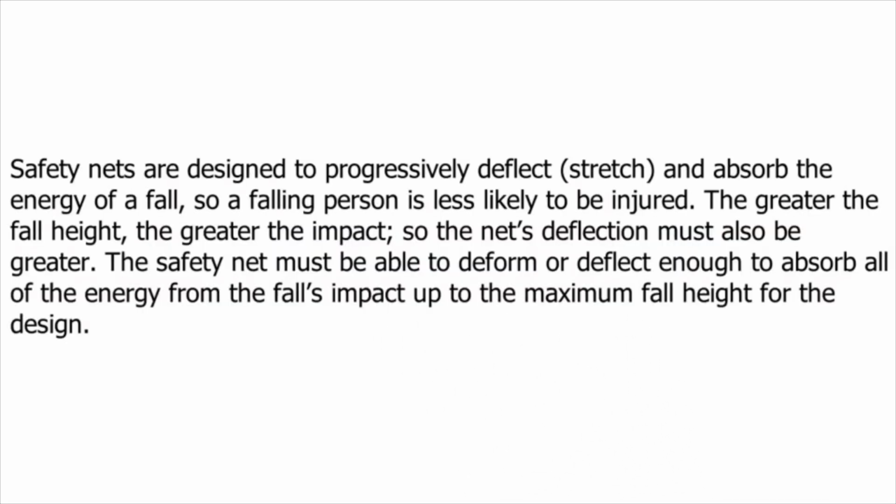Principles of safety net design. Safety nets are designed to progressively deflect, stretch, and absorb the energy of a fall, so a falling person is less likely to be injured. The greater the fall height, the greater the impact, so the net's deflection must also be greater. The safety net must be able to deform or deflect enough to absorb all of the energy from the fall's impact up to the maximum fall height for the design.